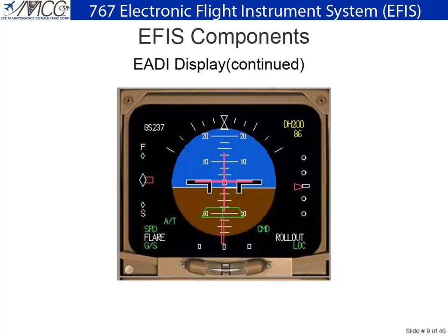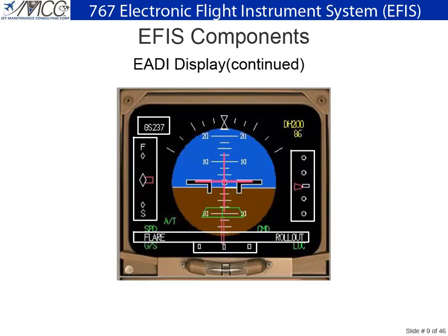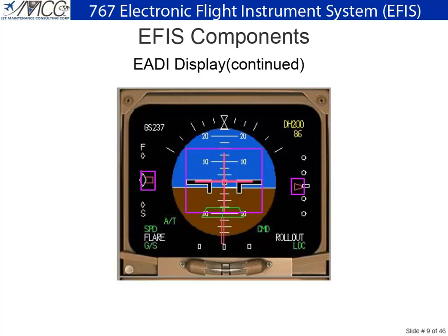The colors used on the displays generally have the following meanings. Green indicates engaged flight mode annunciations or dynamic conditions. White indicates present status situation, scales, and flight mode annunciations. Magenta indicates command information, pointers, symbols, and fly-to conditions. Cyan, or light blue, indicates non-active background information such as the sky. Yellow indicates cautionary information, faults, flags, etc. Red indicates a warning, and black indicates blank areas.